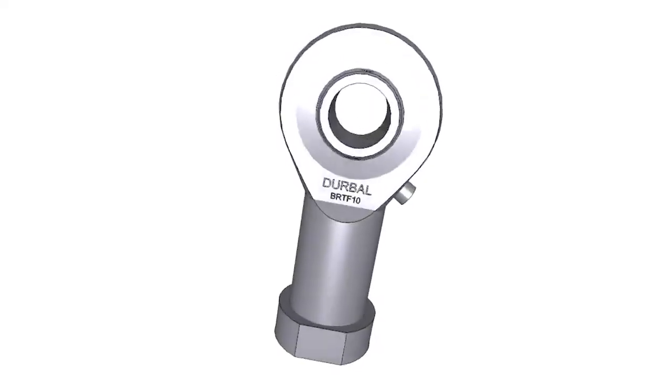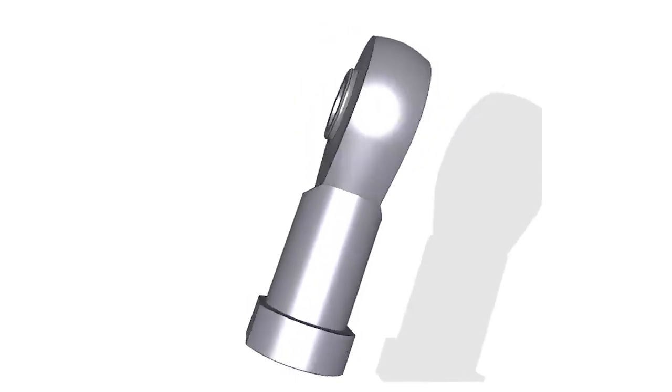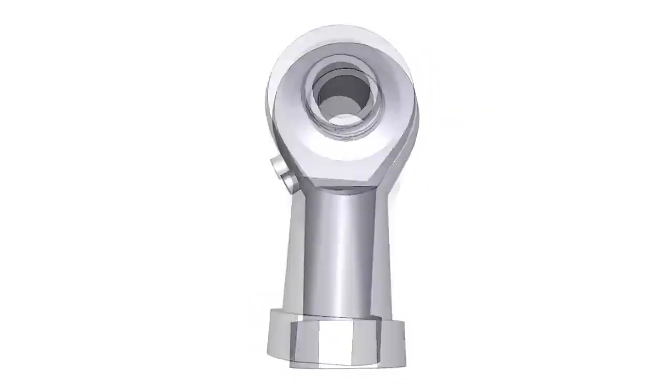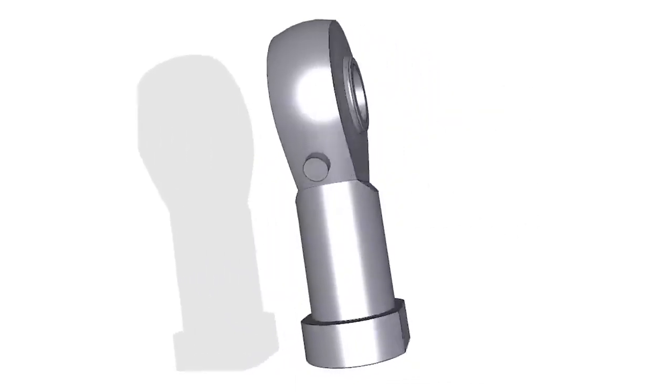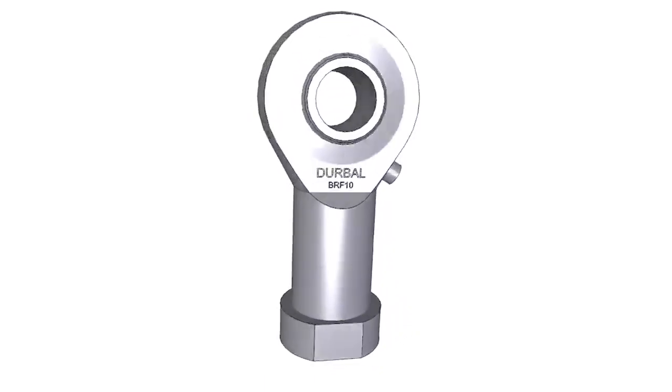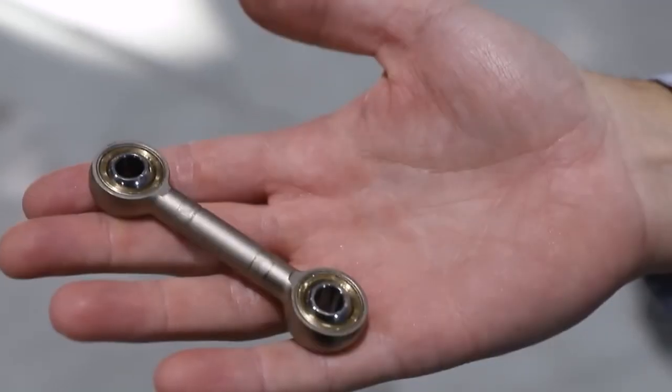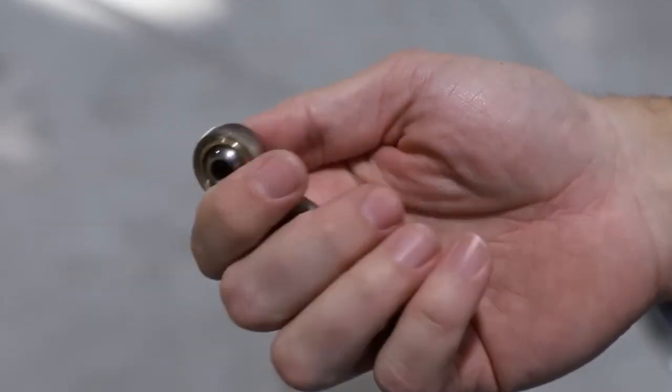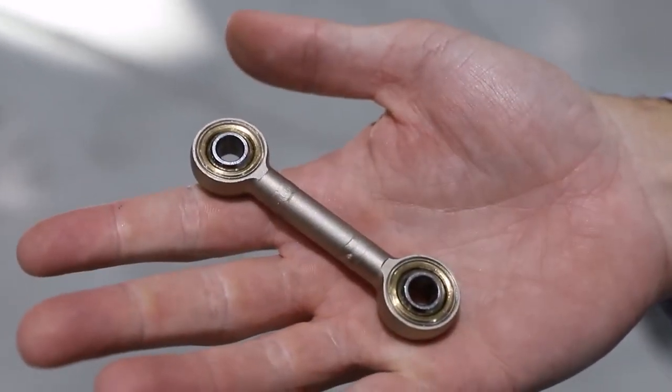Ball bearings or cylindrical roller bearings are used in that case. Our premium series rod ends come in ball and roller bearing versions, and they're DIN ISO 12240-4 compliant. Do rod ends degrade over time? Yes. As the sliding surfaces wear, a gap may begin to develop between the bearing surfaces, which creates backlash. Our engineering team reviews the duty cycle and lifetime requirements of the rod ends we recommend to make sure unexpected issues won't develop over time.